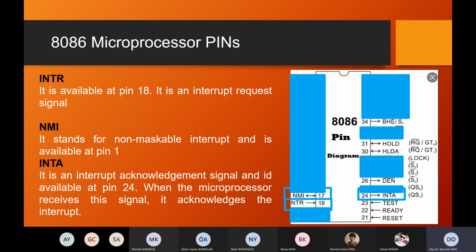This has to be exemplified a little bit. Imagine that, since this is just an electronic circuit, it hasn't got any sense, and it hasn't got any intuition, etc. What it does, whenever an interrupt signal is present in pin number 18, it is programmed, it is designed, to jump to a certain location in the memory to execute a new program.